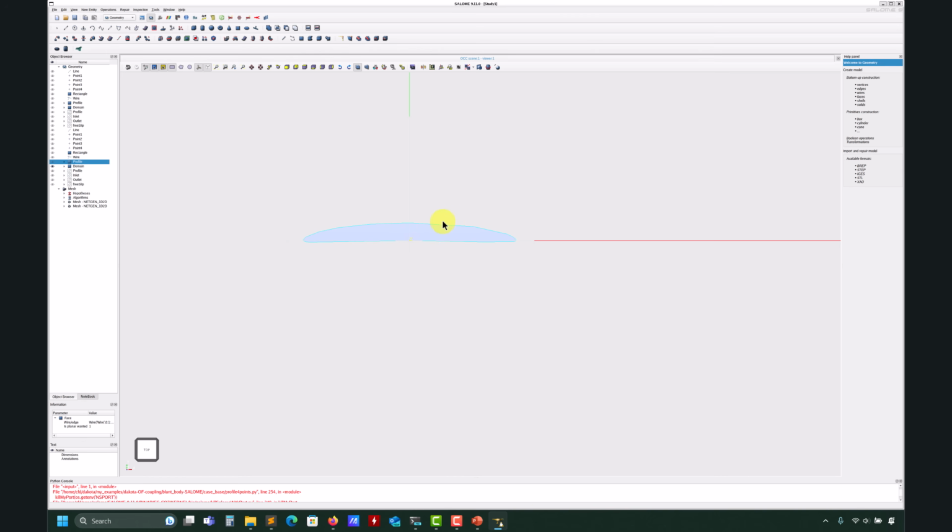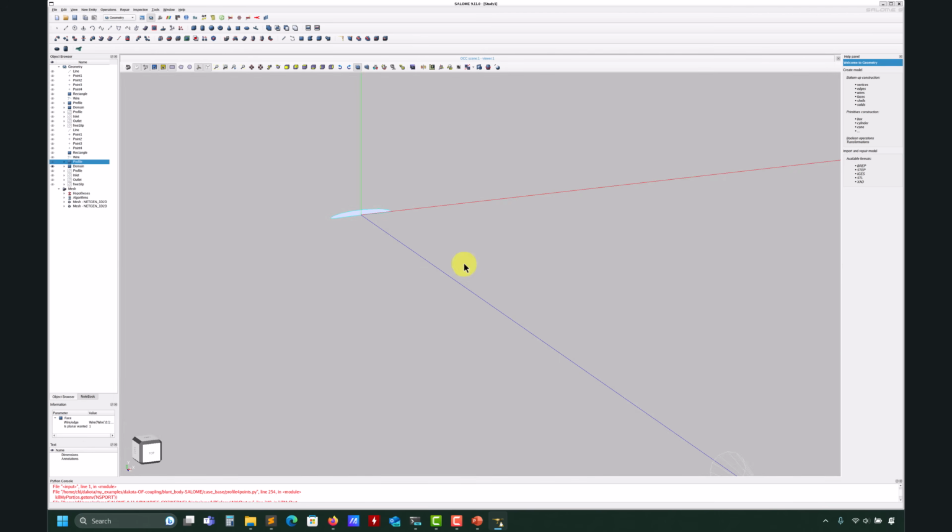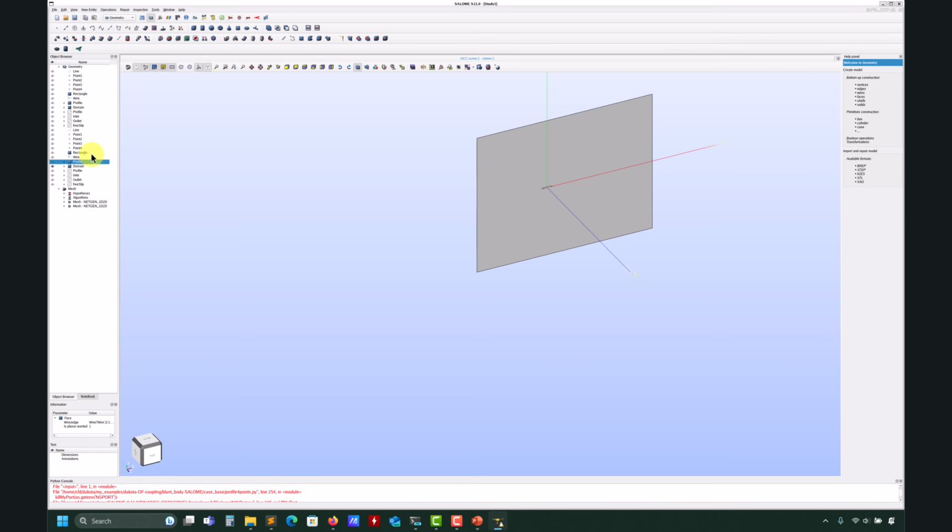So see that here we have the case, the BCA points. If you open the file, you will see what is happening there. And this is your geometry. You create it here. What is also cool about Salome is that you can name the inlets, outlets, profile, and everything. You give names. So yeah, I think I will do a video about this. And then here, when you move, you have the meshing. It's a little bit tricky also how you set up the mesh, because you need to put algorithms and so on, select boundaries, but it's quite handy.